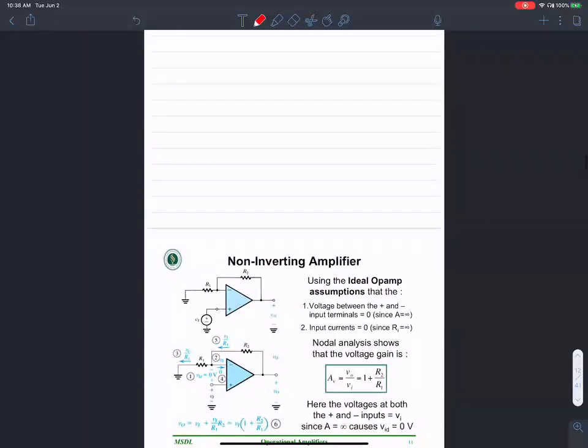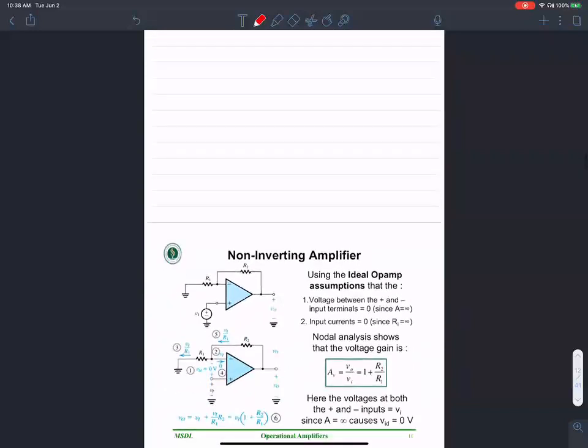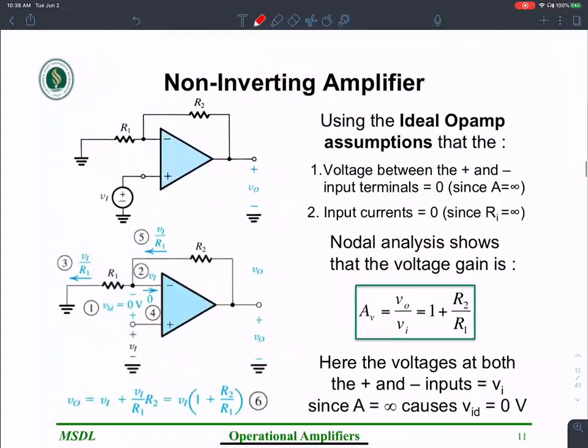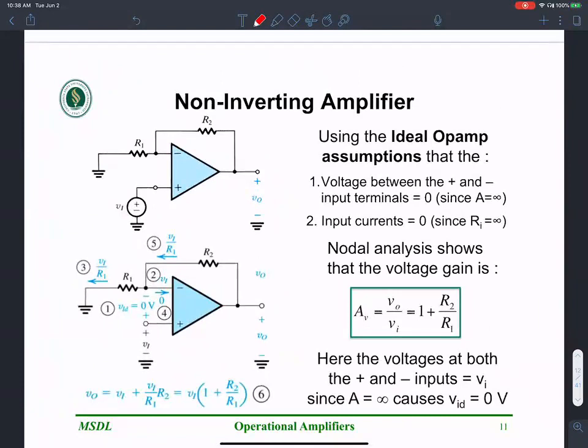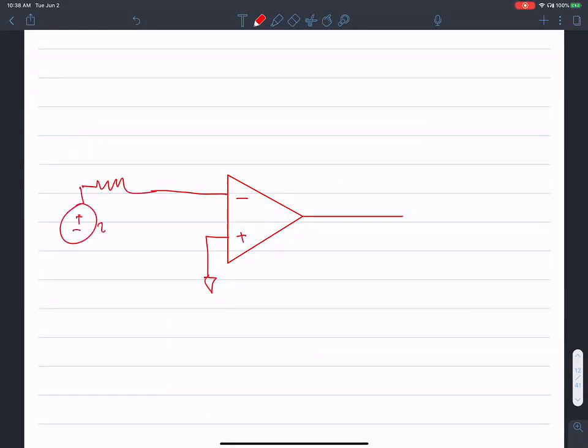So that's the idea of the inverting amplifier. Let me do one more problem here, the non-inverting amplifier. But first, let's quickly recap the inverting amplifier. This is what we did. There is a negative terminal, there is a positive terminal. The positive terminal is tied to ground. In the negative terminal, I applied a voltage Vn. That's the reason it behaves like an inverting amplifier, because I'm applying input at the negative terminal. So R1, R2, V out.